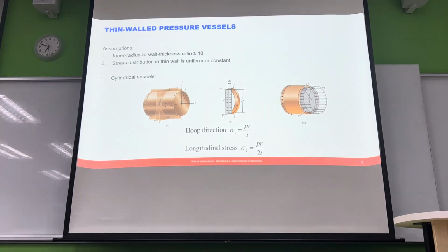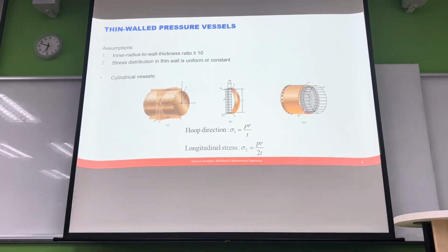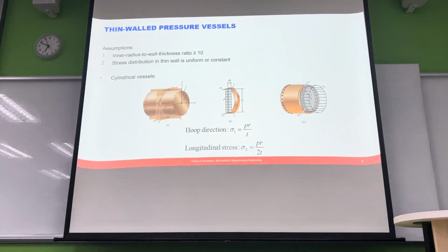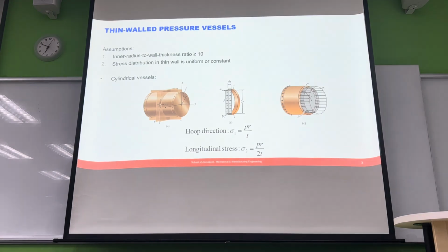Even though we have that same internal pressure still being applied, if we cut it a different way, you can see that the pressure is acting on the end cap. It's pushing on that end cap, and the system has to be in static equilibrium, so the internal stresses you can calculate from the thickness, the area, and the radius. So you end up with this equation here. We can see that these two are different by a factor of 2. So that means this hoop stress is always going to be twice that of the longitudinal stress.